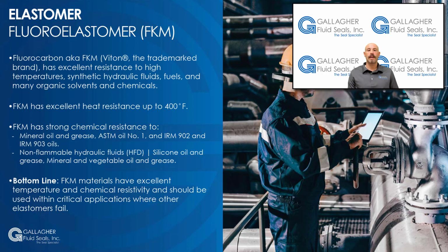FKM has strong chemical resistance to the following: mineral oil and grease, ASTM oil number 1, and IRM 902 and 903 oils. Non-flammable hydraulic fluids, also known as HFD, silicone oil and grease, mineral and vegetable oil and grease.